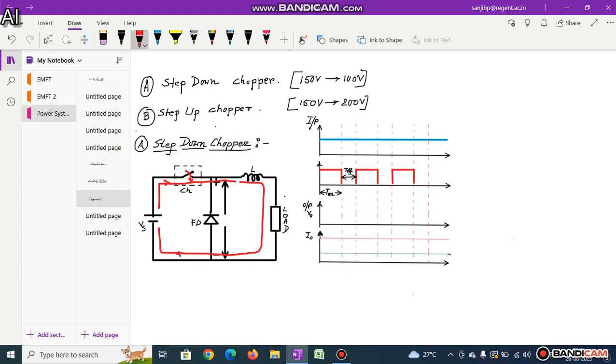Look here, here is the inductor. You know it will store charge. So when the current flows through this, the inductor will be charged, and this will be the polarity. Here the polarity is also mentioned, minus and plus. Here V0 is the voltage across the inductor and load. The load may be anything else, I am not interested in discussing it. So across these plus and minus, the voltage is V0.